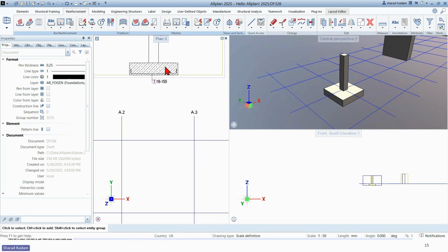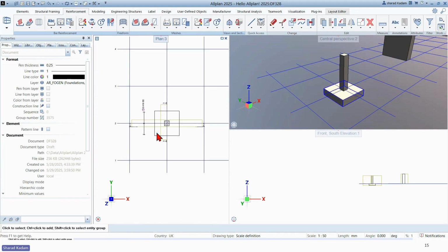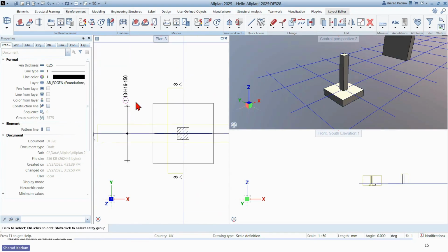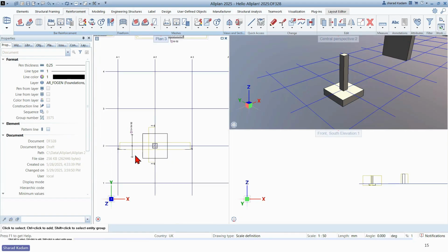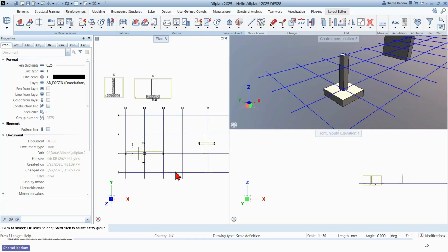So like this, the workflow should be adding a rebar, then giving the call out in the sections, as well as putting the range of it and giving the call out immediately. But there could be companies who are doing the rebar modeling in one go, and once the rebar modeling is completed, clash detection, clash indicate, clash free, all these things are done. Then also we can start with the rebar tagging portion. So it is a complete user choice, the way the person wants to or the way the company standard is, we can go ahead and do it.